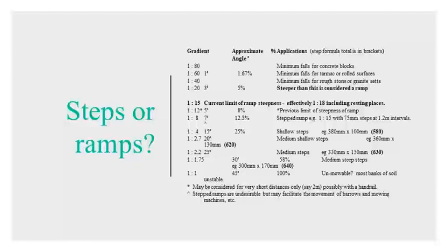When faced with the need to select appropriate dimensions for a set of steps up an existing bank, it is suggested that the average slope of the bank in degrees should be measured on section, and the nearest angle of slope in degrees in the table used as a starting point for the design.